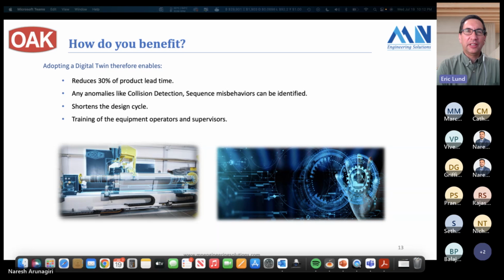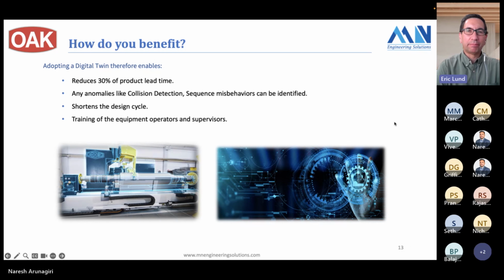And what we did is we used the digital twin as frequently and as often as possible to validate our software functions. As you saw in the video demonstration, we could test not only the PLC cycles, but also the HMI. As you interface with the HMI, you could press the buttons, see the feedback, and look at the ladder and see what steps we're going through. It truly was like using the real physical machine.